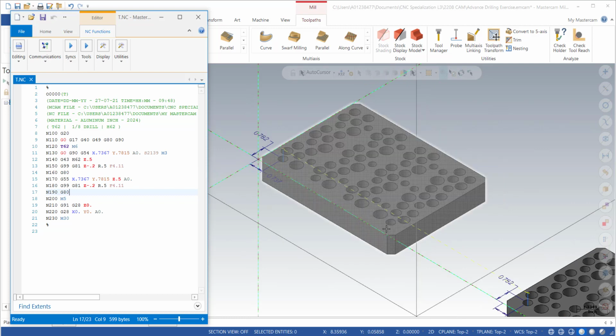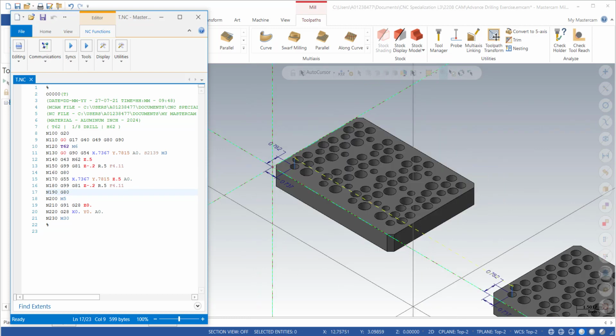All the operator has to do is just pick up their respective corners and enter that information in their respective work offsets, right? G54 and G55. So you can see both of them are basically the coordinates we are getting from the part origin.